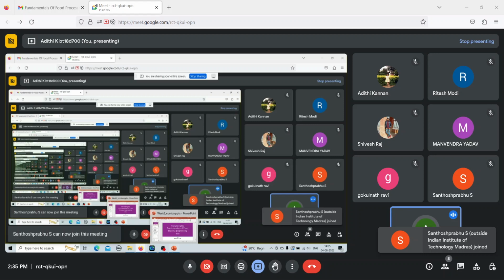You'll have a marking at the top of the cylinder and a marking at the bottom of the cylinder. When the ball first reaches the top marking, you'll start the timer, and when the ball reaches the second marking at the bottom, you'll stop the timer and calculate how much time it has taken for the sphere to pass from point A to point B in the cylinder. With that, you can calculate the viscosity of the fluid, which is related to the time taken by the sphere to pass between two specified lines on the cylindrical tube.